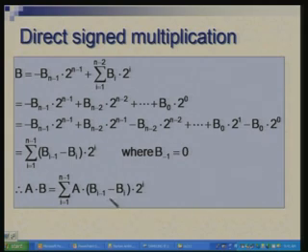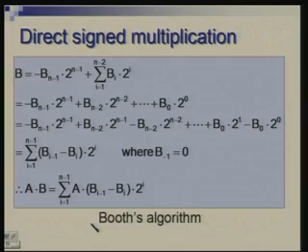Okay. So, still things are not too difficult. Minus 1 would mean that I actually take minus a. So, this partial product would be 0, a or minus a, and adding minus a means basically subtracting a. Right. So, I have something which is very similar to what we had done. There are just a few differences which I will enumerate. Incidentally, this is called Booth's algorithm.